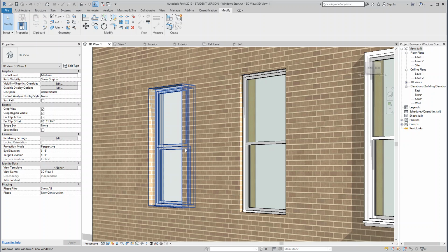And you can see the error, like I said, this window, the panels, or actually the frames, overhang each other, so you only get one appearance. In this case, we have two lines showing there. But I thought this was just a quicker way for us to get to the look of a window. Otherwise, we'd have to make two reference planes for the top and bottom of that and do some other alignment.